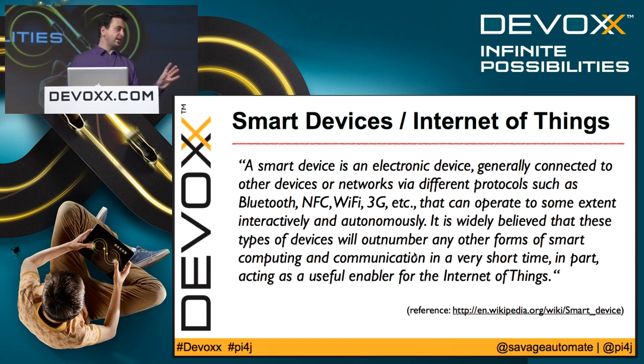Okay, so that concludes the portion that's just an introduction to Pi4J and how you would use GPIO, how you signal these pins and what they can potentially do for you. Drive outputs to control things, listen to inputs to sense things. But what can I use all of this for? Because what I want to create is a smart home, smart devices for a home.